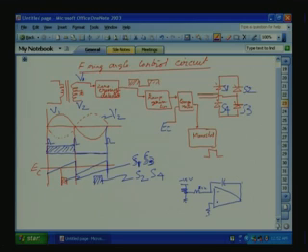So, for that, we will connect a transistor here. Maybe we can put a small resistance also here and give the pulses here. Whenever the zero comes, it will quickly discharge. Output is always positive, negative, it goes like this. So, a ramp we can generate. This is a typical circuit. Whenever the pulse is there, it will quickly discharge, and when the pulse is not there, it will charge.